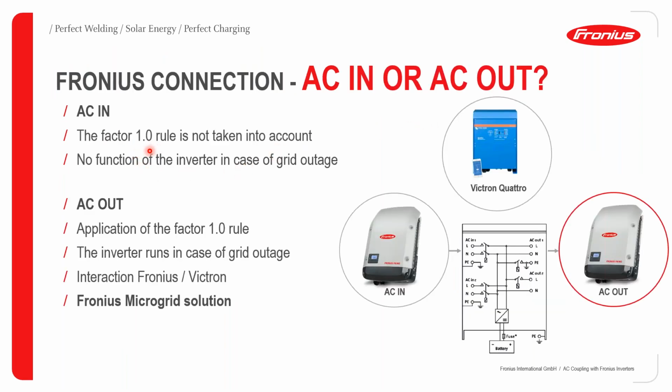When it comes to the connection of the Fronius inverter in an AC coupled setup, we have two possibilities to connect the Fronius inverter. One is the AC in, as we see in this graphic representation here. So with the battery inverter, you can connect the Fronius inverter in the AC in.